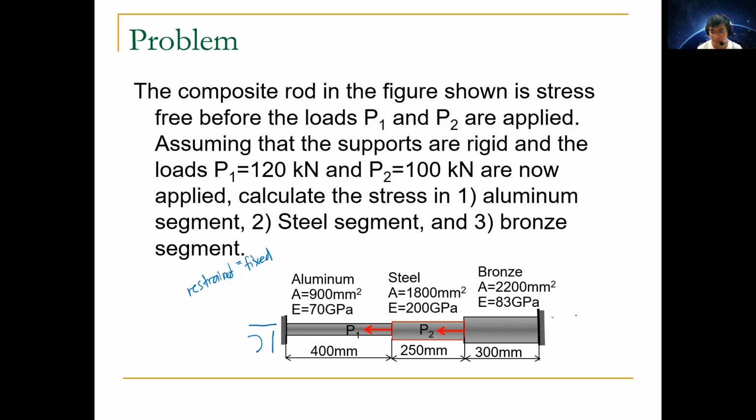Moment. So wala siya arrow because we don't know yet the direction of the reaction forces, diba? Especially for the moment. As far as we know, since we are presented with the 6 unknowns, comparing it with 3 equilibrium forces, our member is statically indeterminate.